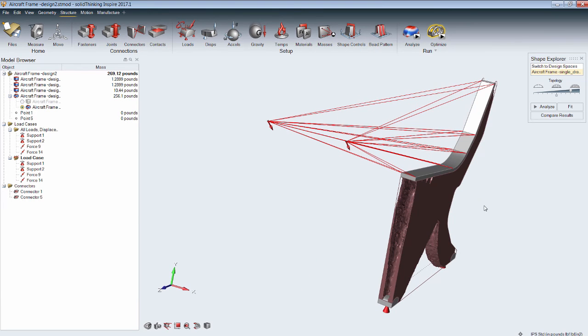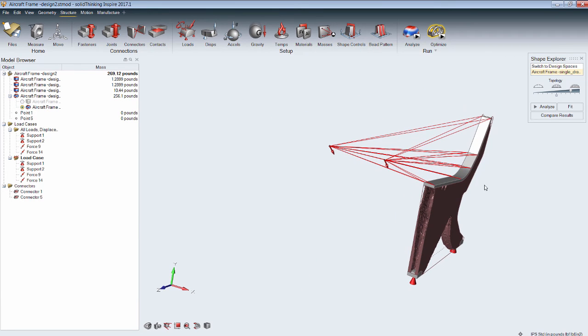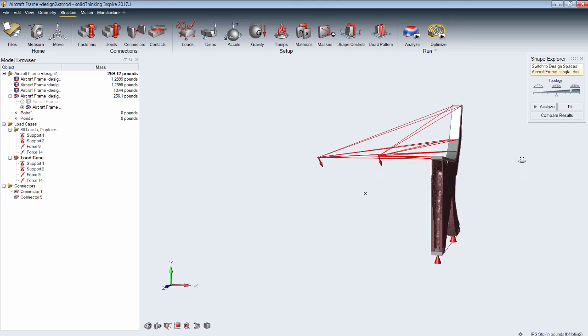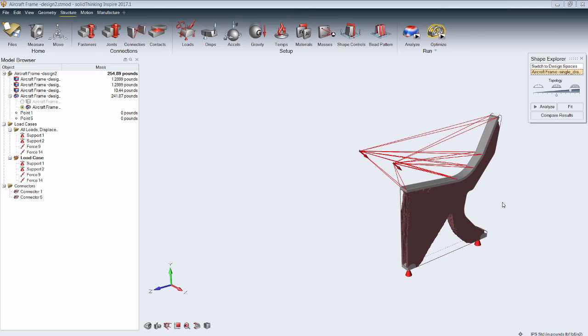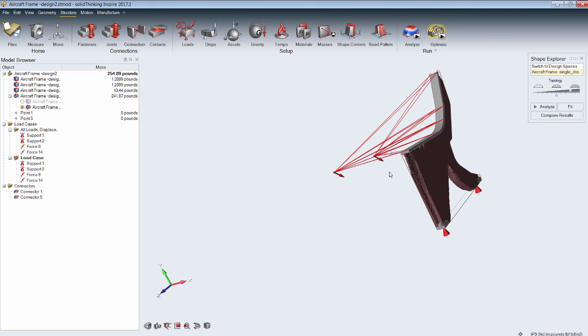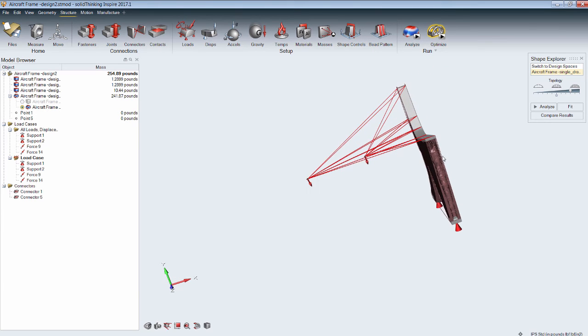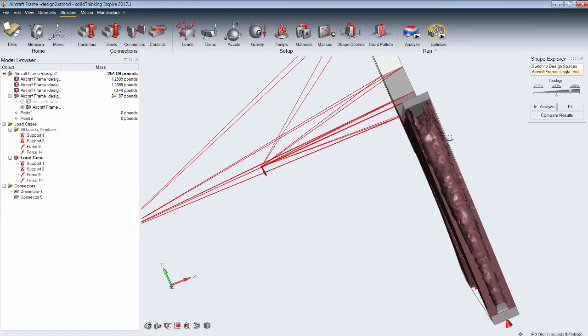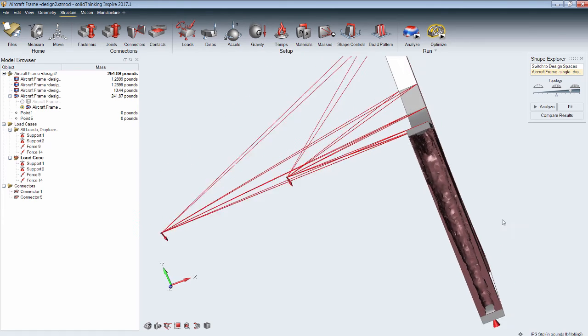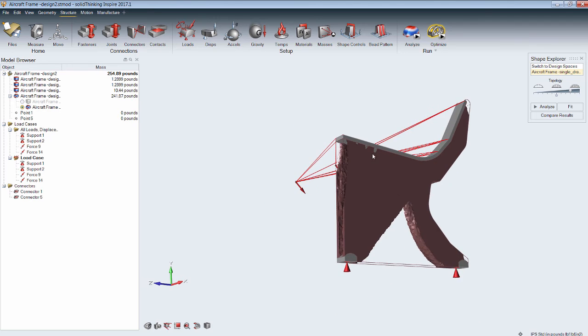So here's the study after it ran to completion. Once again, similar setup, and here is the optimized results. There's a slider that fills or removes material based on how much fill you want. Staying about 70% to the right, it still removes a lot of material. If you look at the optimized geometry, you see that it's removed material from the insides. So at this point,